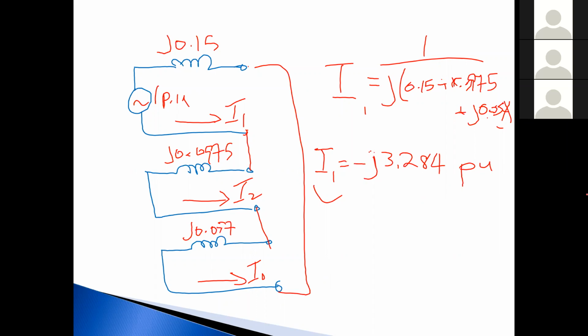What we have here is I1. I1 is a positive sequence current. What are we being asked to calculate? Is it the zero sequence current? No, sir. Zero sequence, positive sequence, they're part of the theory. But I want to know the per unit current that is flowing into the fault. So what exactly am I being asked to calculate? The current in the network at the time of the fault, sir. Which would be what? The phase currents. Thank you. So I'm being asked to find IA, IB, and IC.